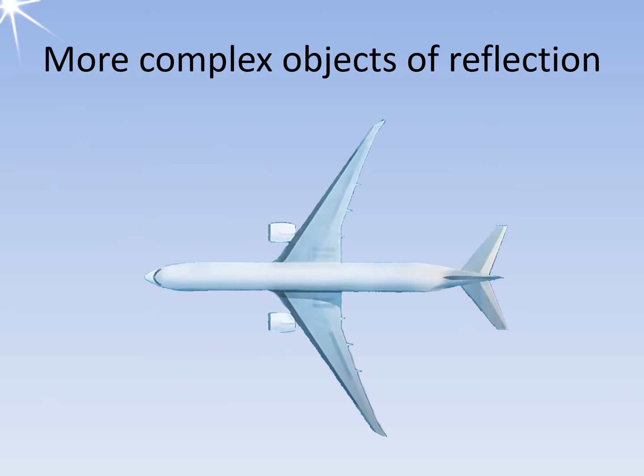The echo signal of an aircraft is composed of various individual components. Diffraction occurs mainly at sharp edges and corners, in addition to specular reflection. First, tip diffraction. Scattering from tips is less significant than specular echoes. It tends to increase with the square of the wavelength, not the size of any surface feature.